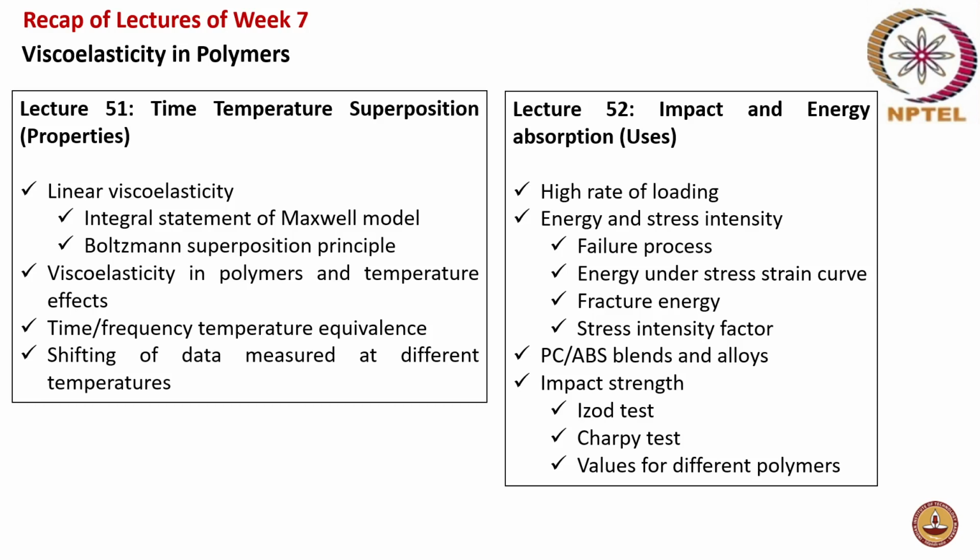Yes, ma'am. And then your impact strength, and then two different types of testing, the Izod test and the Charpy test for impact strength were discussed. This was followed by what the impact strength is for different polymers, right? LDPE, if you remember, had very high impact strength, of the order of 1000. Do you remember? Yes, ma'am.